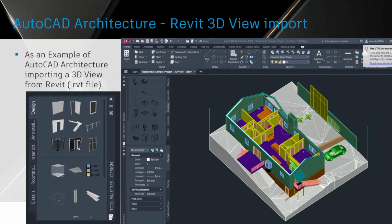As an example of AutoCAD Architecture importing a 3D view from Revit, an RVT file, a project file, the tool palette designed, for example, as displayed here, is part of the installation and has a wide variety of AEC objects and elements for easy use, which displays in all views, plans, sections, elevations, details, etc. These elements also schedule. Creating door and window schedules is also easily done, as the intelligent objects are updated with the schedule. No matter in which view you make changes, all views and schedules update.